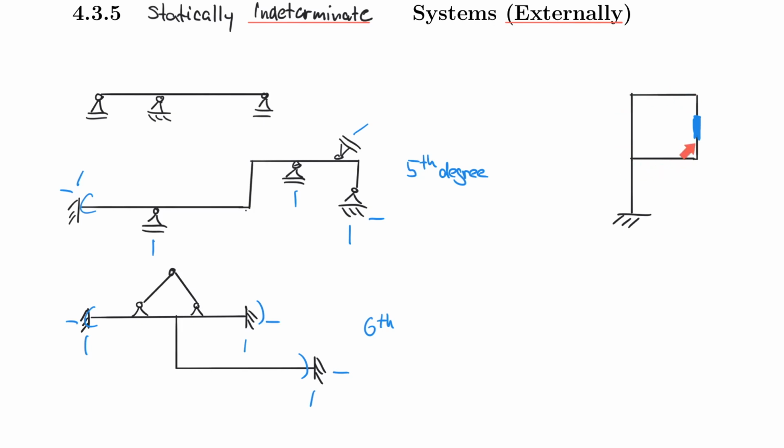And you can see this is kind of like a closed frame. So think of heat being added to the system. What happens if you add heat to it? Every part of the structure wants to expand. It wants to become longer. And therefore, the forces will actually transfer from one part of the structure through the welding to the next part.